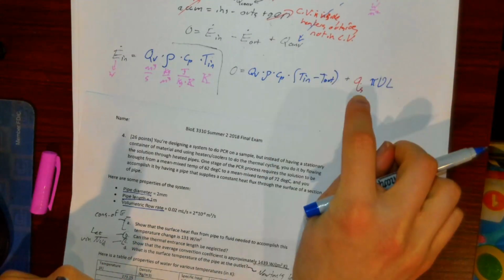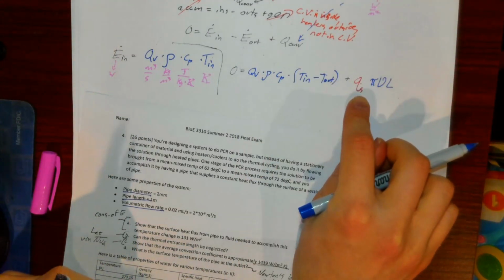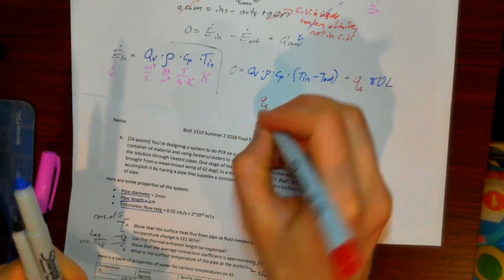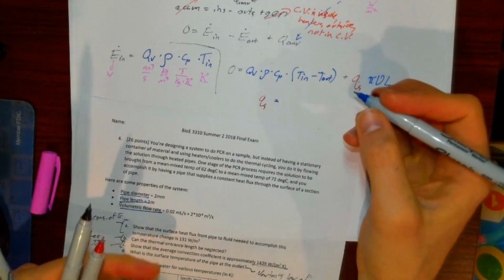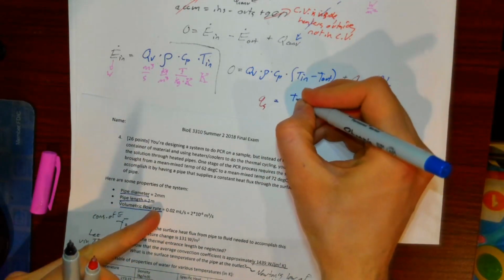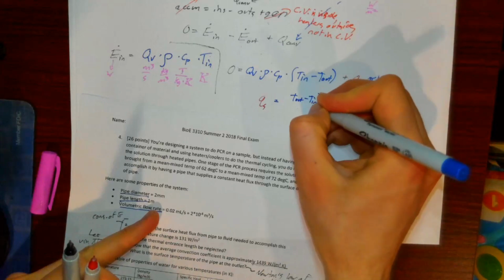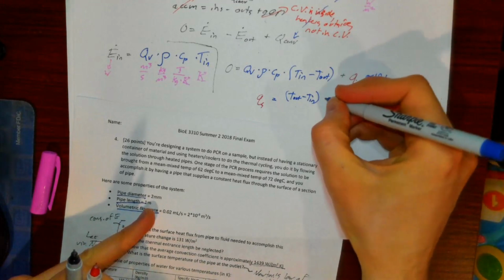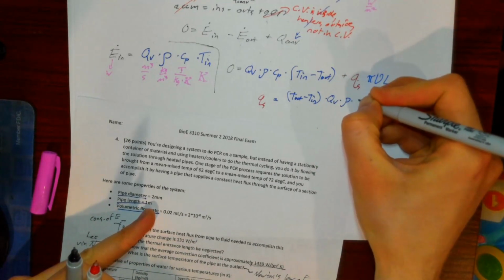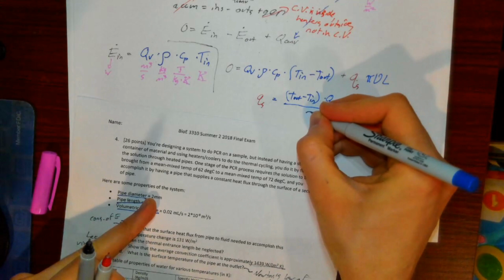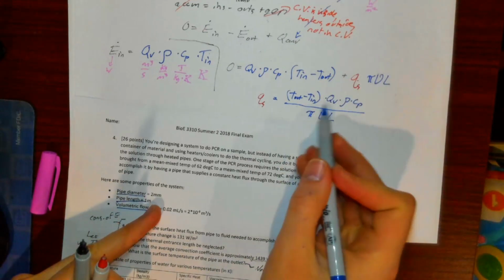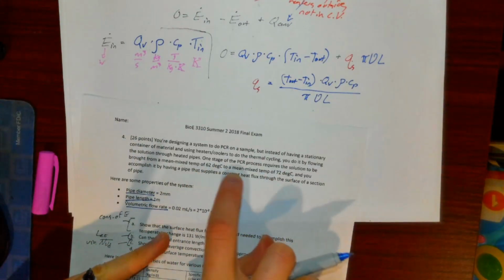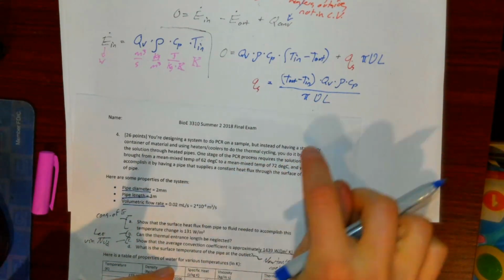So what does this mean? This basically gives us all of the information we need to solve for our as yet unknown surface heat flux. And that's basically equal to T out minus T in. Again, if I bring this stuff over to the other side, I'd be flipping the order by essentially factoring out a minus sign. Volumetric flow rate, rho Cp, divided by pi dL. So these are knowns. T out and T in, those are given in this part of the problem. D and L, those are given.